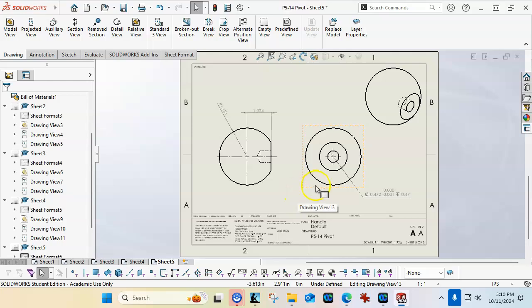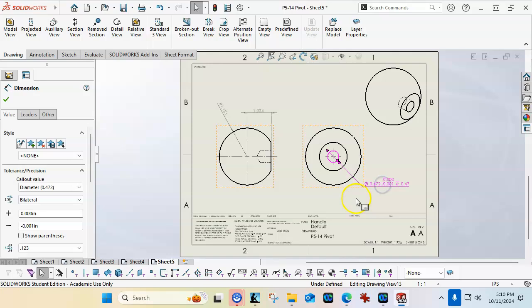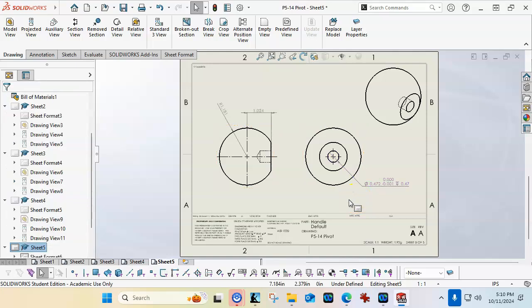I mean, at best, this ends up 472, and the other one ends up 472. It's a transitional fit. There's barely any press there, but at least it wouldn't be flopping around. Worst case at a 2,000ths, we would need a little bit of force to jam these two pieces together and make those work. So we want to start thinking about that process.